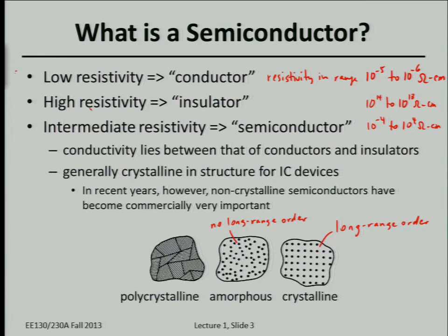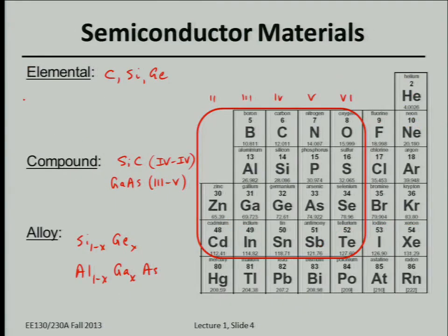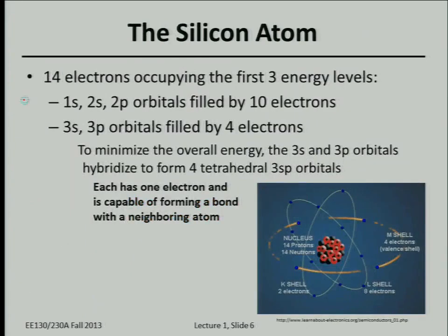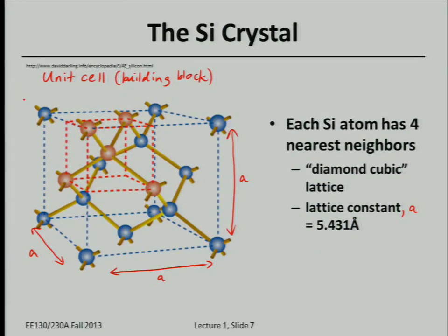Last time we mentioned that there are some typical metals, highly conductive materials, aluminum and copper, used in integrated circuits. And I forgot to mention that the most common insulator used in integrated circuits today is silicon dioxide. That's highly insulating. It's in the upper range of the resistivity, 10^18 ohm-centimeter. And for an undoped semiconductor, the pure semiconductor, the resistivity is 10^4. I didn't explicitly write, but this is the unit cell of a single crystalline silicon crystal.